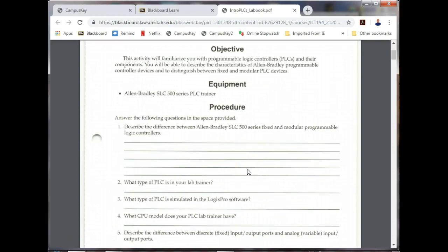So what we have is we have these guys down there. Anytime you talk about the SLC 500, these are the PLCs you find. These are not the ones we're going to use in class because the interface in it is so slow. It's using RS-232. The interface that we're using is called RS-485.